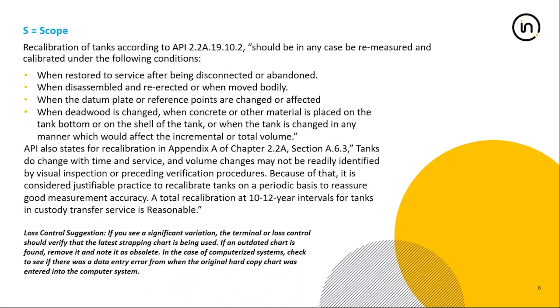The faster frequency that you have between every recalibration is actually going to be better for you, because it's going to allow you to keep better control of your intervals, because you know that you have an accurate measurement of your tank volume.